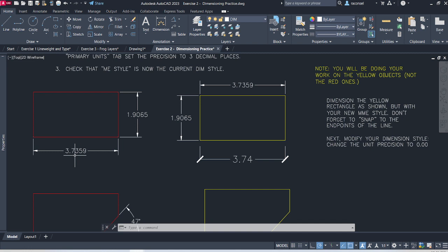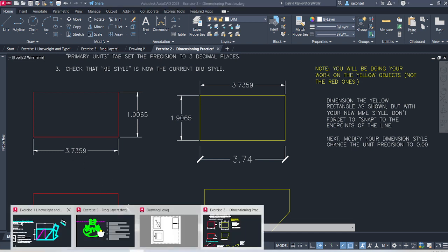And this is a thing that, industry to industry, project to project, you're going to end up with different tolerance levels. If you are working on something like the James Webb Space Telescope mirrors, you might be working to a finer degree than this. You might be in hundredths of a thousandth of an inch. You might be working in micrometers, but usually you're working in tenths of a millimeter, maybe. That's pretty precise. If you're working in wood, you're usually working to an eighth of an inch as your tolerance. If you're framing a house, that's even a bit restrictive.